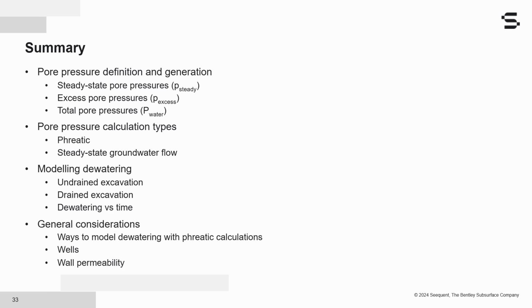And of course, sandy soils tend to have higher permeability than clay soils. Plaxis gives you the option to use some default values for the permeabilities based on the type of soil that you have. So if you go to the material definition, then you go to the groundwater tab, then you have the option to use the default values, which in my experience are not accurate, but at least pretty good. So you can use that if you don't have anything.